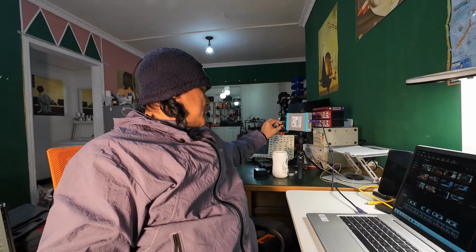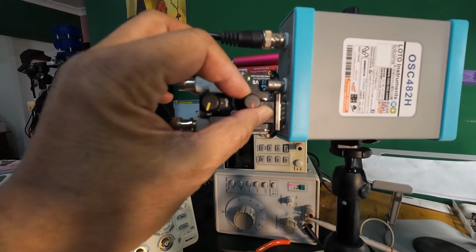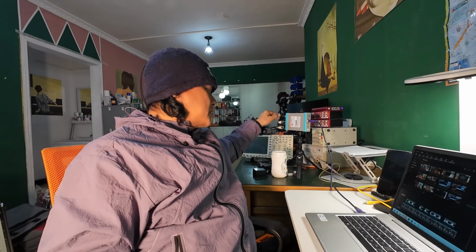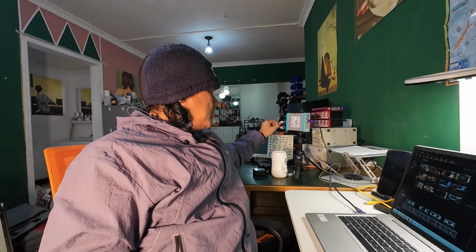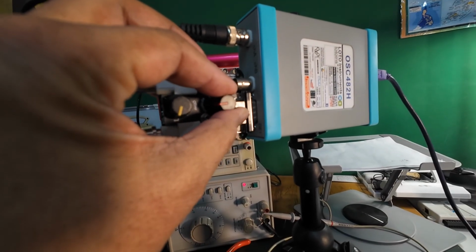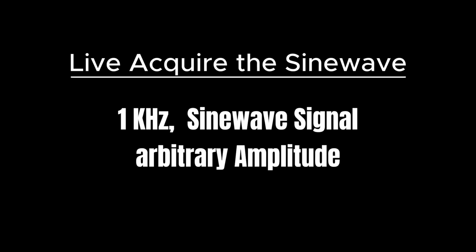You have to adjust it in here. There is a knob here at the signal generator module, wherein you can increase it counterclockwise. Yes, counterclockwise. Simply turning counterclockwise increases the amplitude, clockwise will decrease the amplitude. That's how you're going to adjust the amplitude of the signal. So now everything is set up, the oscilloscope part and the audio signal generator part. It's done, completely set up.